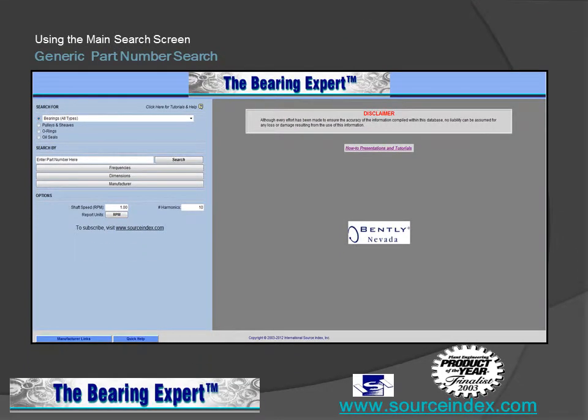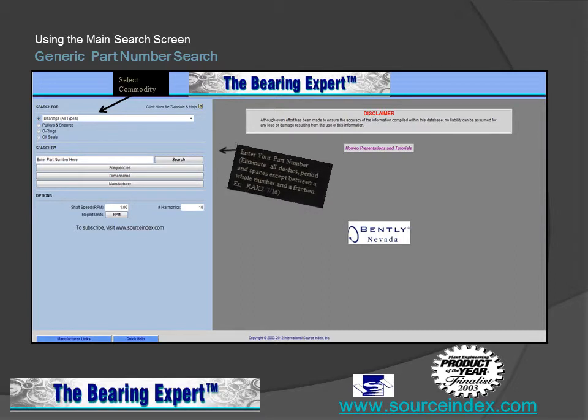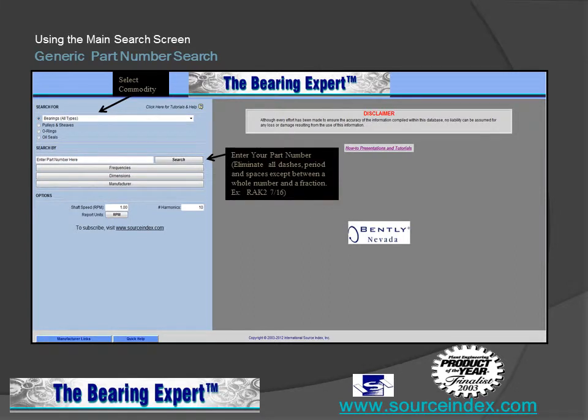Now we begin to look at the main search screen for the Bearing Expert. Initially, in the upper left-hand corner, you have the option to select your product category. The Bearing Expert defaults to bearings all types. In the Search By box, you have the option to search for bearing data by part number, dimensions, manufacturer, or by frequency. Frequency is related to and used for vibration analysis and condition monitoring and will be explained in more detail in the reverse search tutorial.